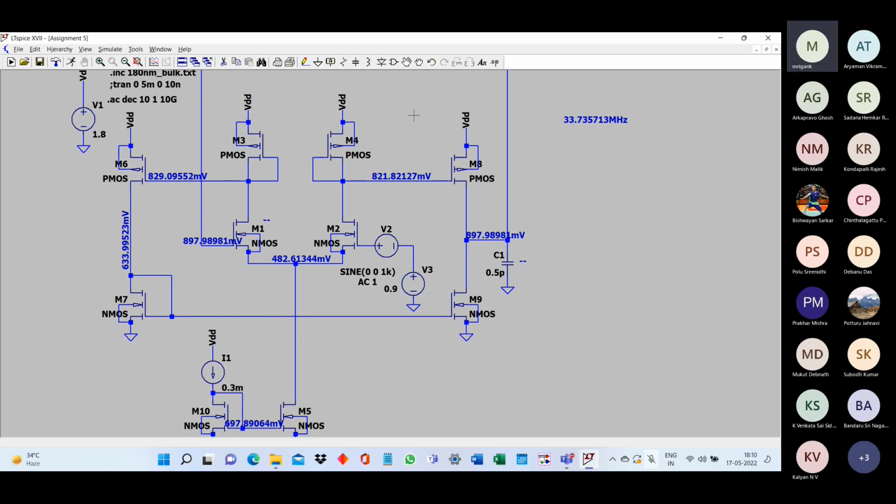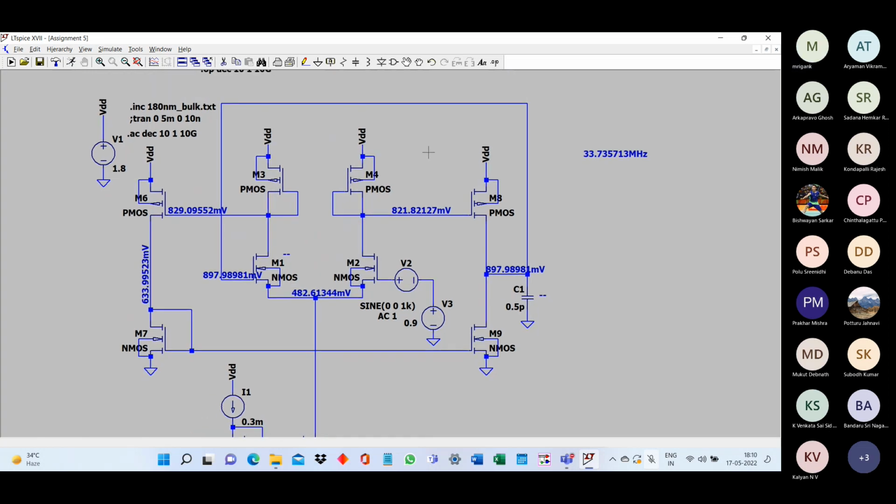Okay, so if you want to increase the gain at the second stage, one option is that the mirroring ratio can be increased to increase the current, and then L can be increased to increase the gain. These are the two options we have. I hope you understand the philosophy in this particular Opamp topology. And here we can see that as compared to 13-14 millivolt, we are down to 2 millivolt error, which is okay. So I hope through this discussion, most of you can complete whatever assignment we had.